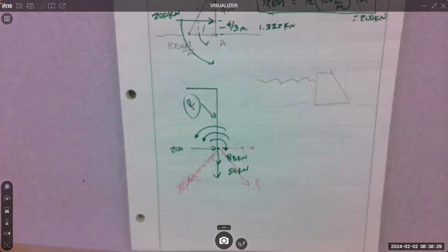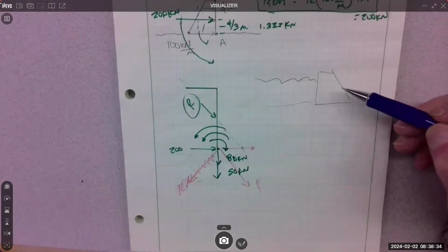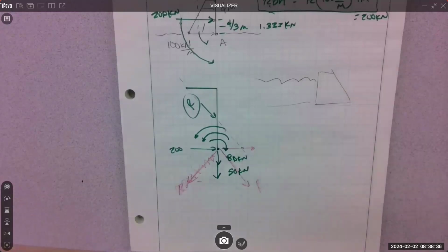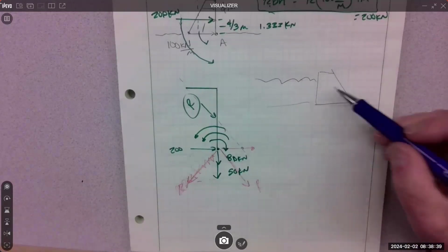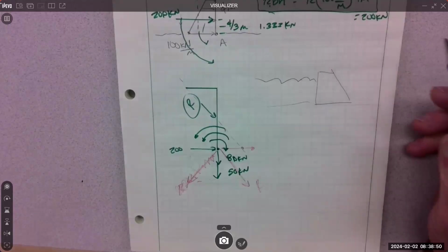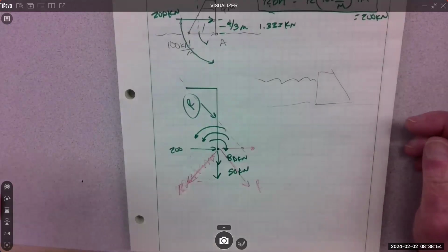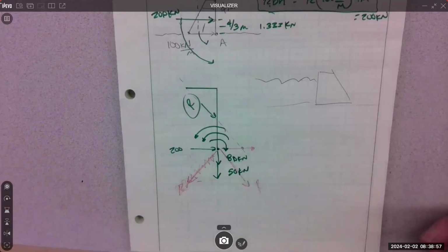Right? So that's a gravity dam. That's water. This is a gravity dam or earth dam, where you just take earth and hold water back, which is a primary way we do dams. Drive along the Columbia, if you're driving on Marine Drive, that is a gravity dike holding water back. It keeps the water from going into the Portland airport and the rest of the area, it's a giant area that we're holding. We add so that it's taller than the maximum flood point.